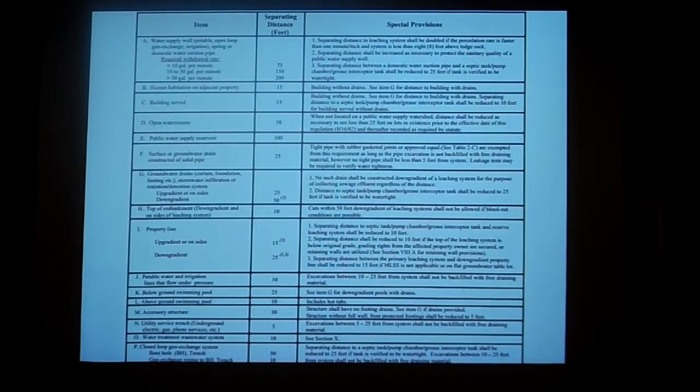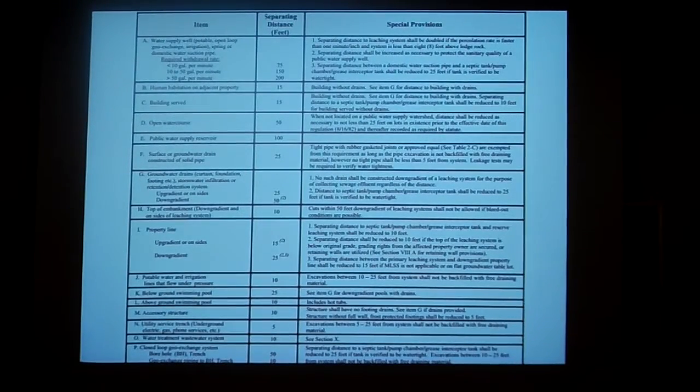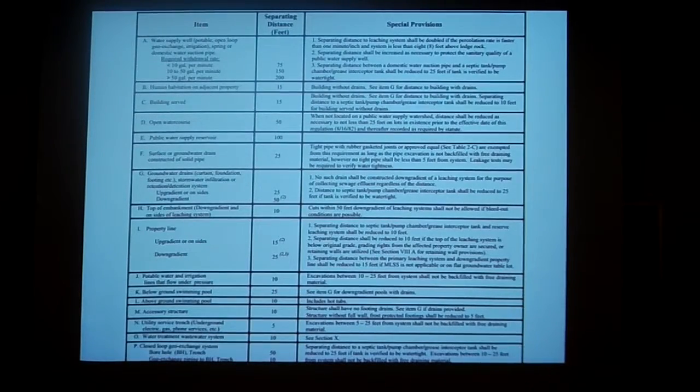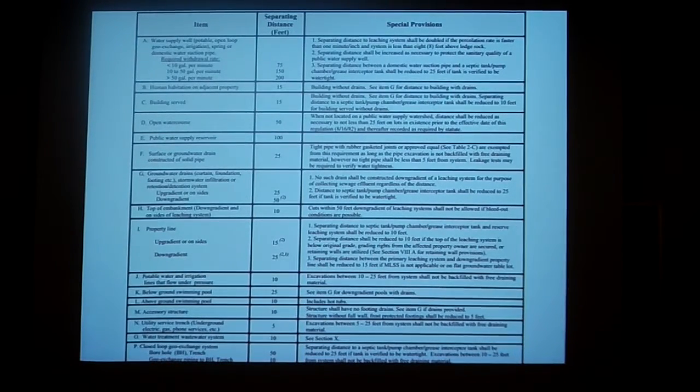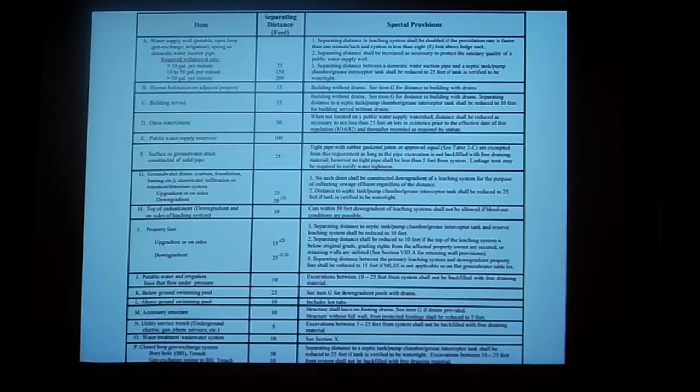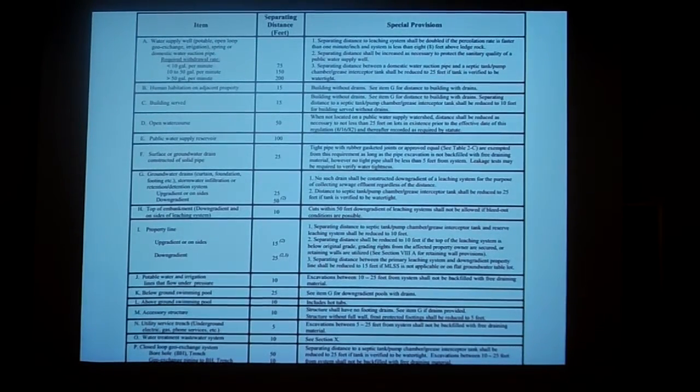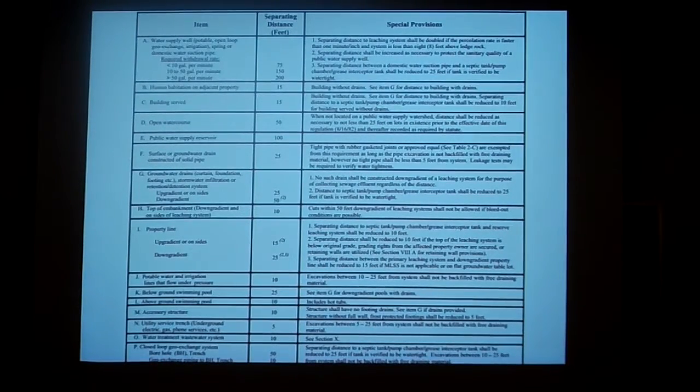There are several other minimal requirements that are outlined in this table from the Department of Public Health's documents. For example, item 3, listed as C in the table, building served needs to be 15 feet. The septic tank needs to be 15 feet from the building.